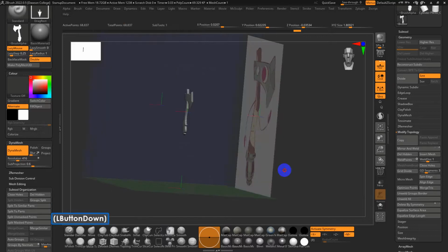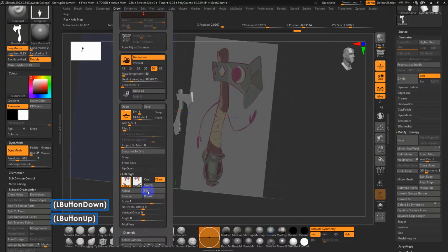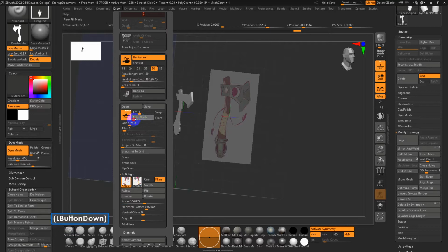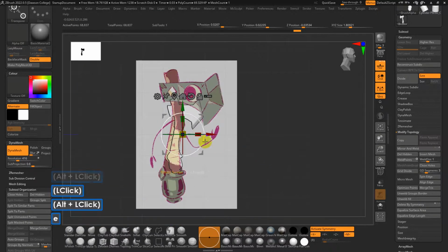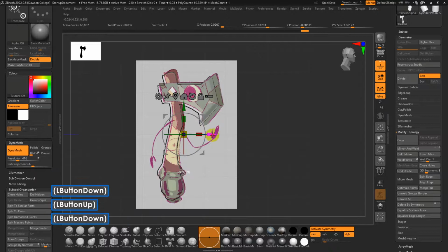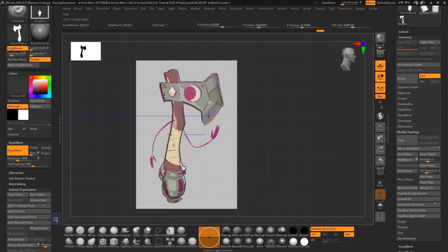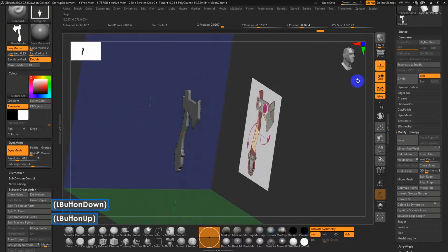And we do have adjustments, so just so you know, you can take these under the draw menu. We can flip the drawing, by the way. So if you go into draw again, you can flip it, you can scale it, you can offset. We also have a fill mode option. If the fill mode's at 0, then we don't see the fill. If it's at 1, it's a semi-transparent mode, less transparent, and then there's almost like full view. And when we're in a side view, we can literally get almost this X-ray view of the prop. So we can resync this to our silhouettes or our drawing, okay? So I just wanted to show you that as well for referencing in ZBrush.